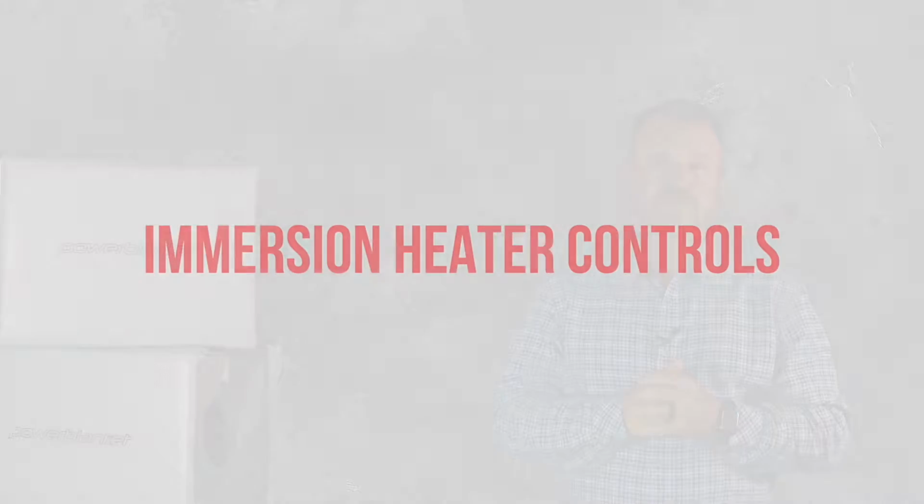A lot of tanks that are in operation that need a lot of extra heat, like in the oil field, for example, for day tanks, they have a lot of extra 2 inch and 2.5 inch connections at the bottom of the tank. So it's really easy to drain the tank and stick the heater in the application and twist them in. Screw plug heaters are very reliable, very rugged. They can be controlled with a local thermostat, and they perform very well in a lot of rugged applications.